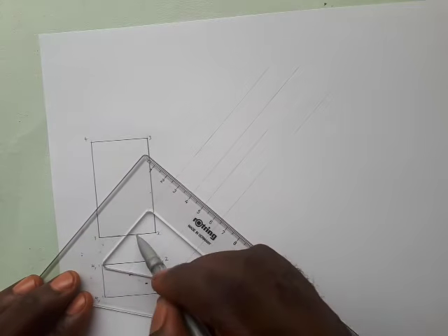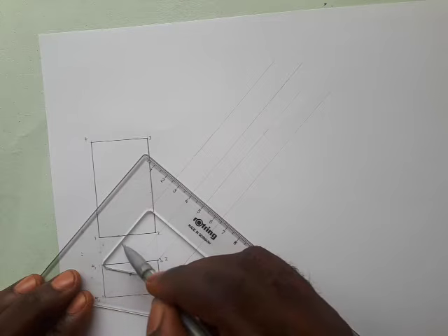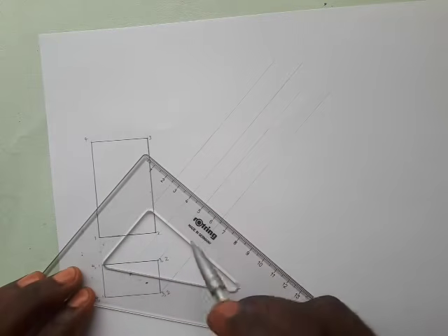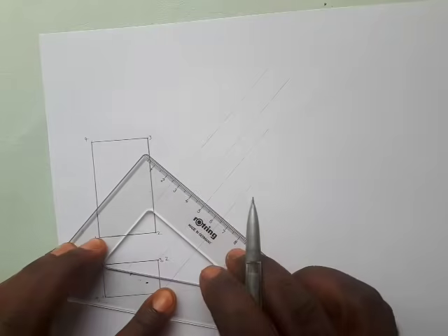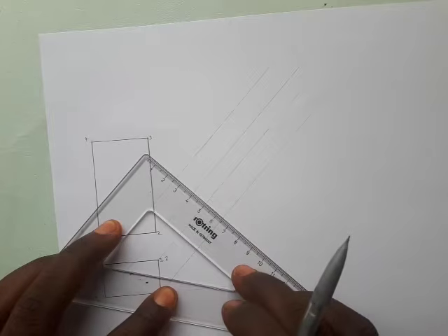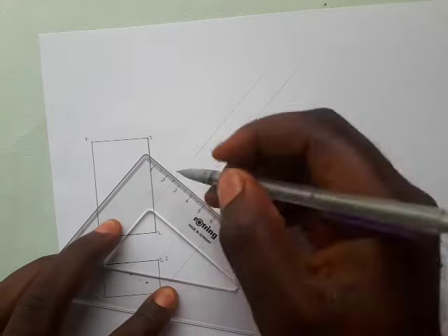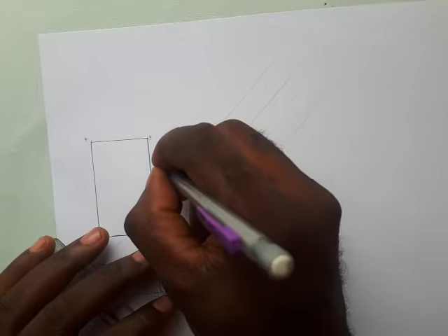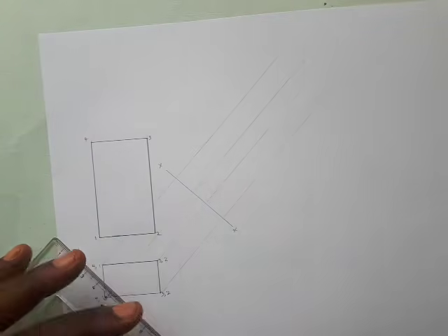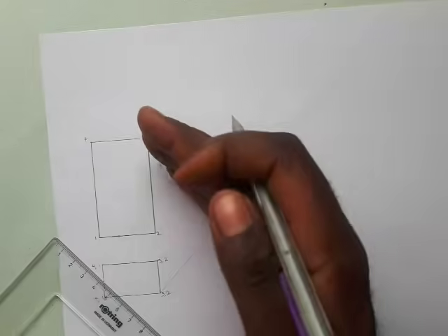So I'm going to align this with my set square. You can actually use any of the lines, at any convenient distance of your choice. Just ensure it doesn't encroach into this elevation. So this is properly aligned, and any line I draw here now is perpendicular. So this is the XX line I'm talking about. You draw a thin line as well. So this is where I will start my drawing from.